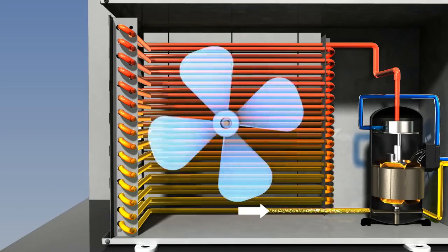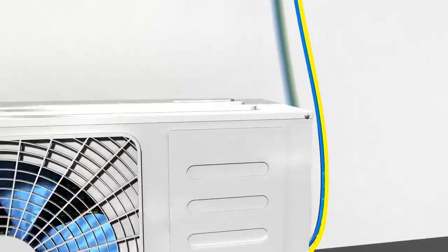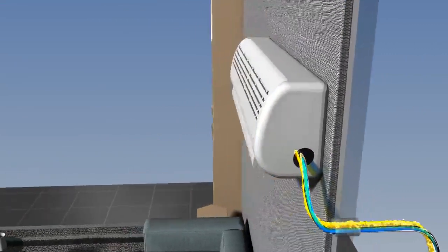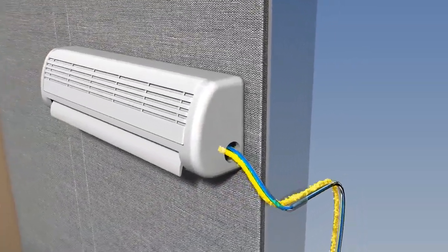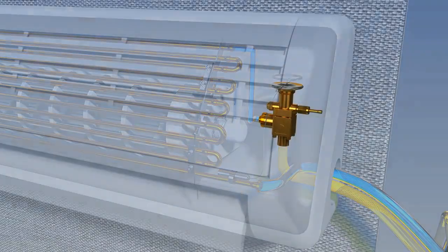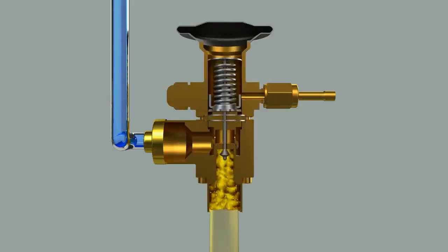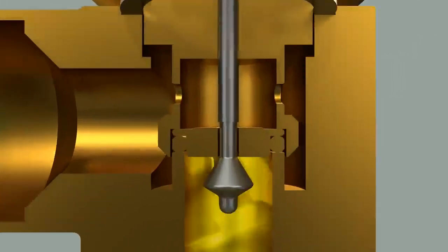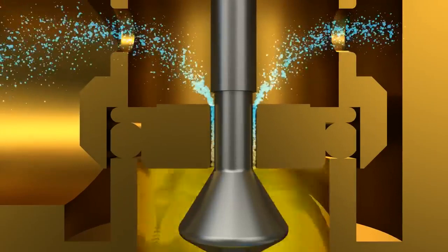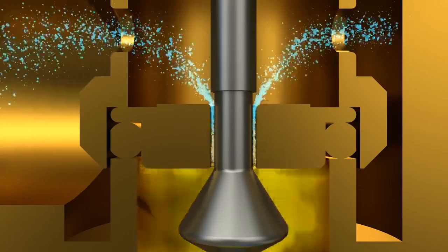As such, it becomes condensed and at the exit, it turns into liquid almost. Although the refrigerant has thrown off some of the heat as it passes through a condenser, it is still hot, with temperature at about 50 Celsius. The refrigerant in high temperature and high pressure liquid flows into the expansion valve. The refrigerant which used to flow in large space now passes through a narrow area, and its pressure drops as it goes. When the pressure drops, temperature drops dramatically as well. The cool refrigerant is now sent to an evaporator.